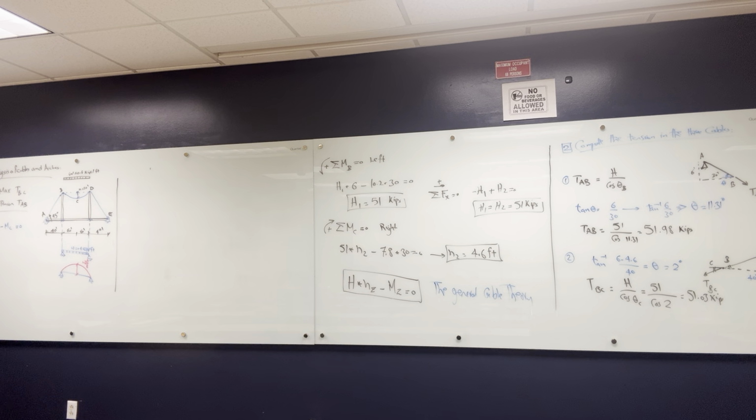So I don't know what is the horizontal force in the cable, but I know the height at C, the sag, is equal to 10 foot minus the moment at C, which is wL squared over 8. w is 0.6, and L, by the way, is all this length, so it's going to be 120 squared over 8. All this is going to be equal to 0. You will find that the horizontal force is going to be equal to 108 kips. I need this to solve the problem, okay?